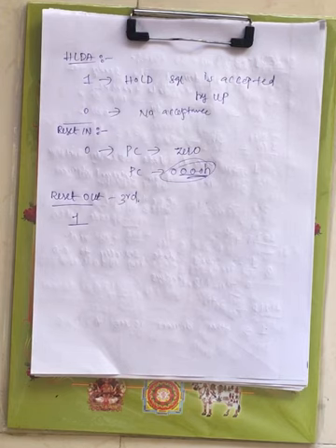If other devices want to use the address bus, data bus or the control bus, then they will generate the hold signal. Once the processor accepts the hold signal, that information is given through the hold acknowledgement signal. Now coming to reset in bar, which is an active low signal. When it is 0, it will set the program counter to 0.